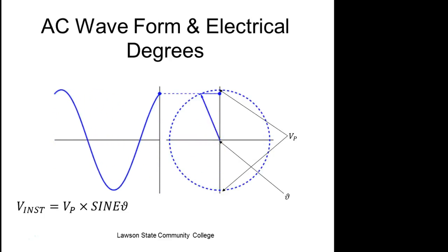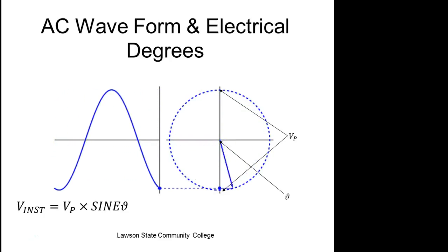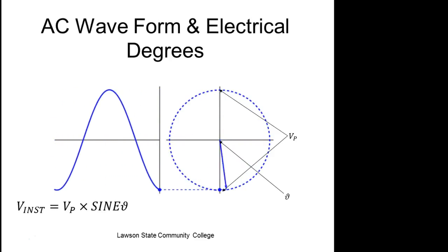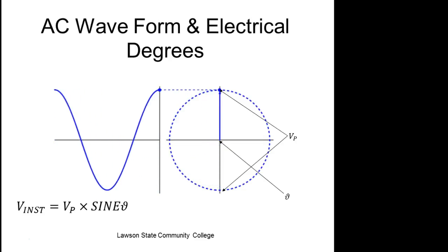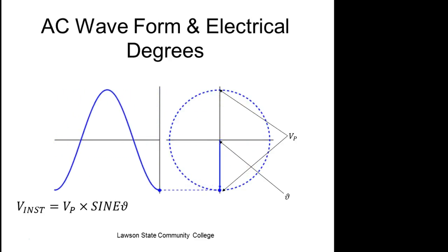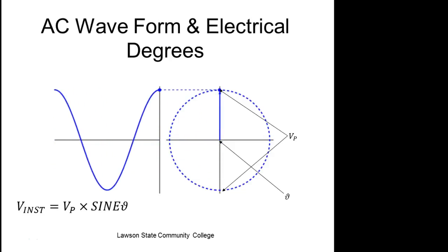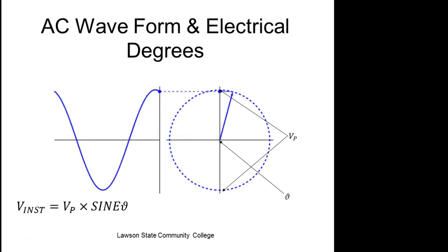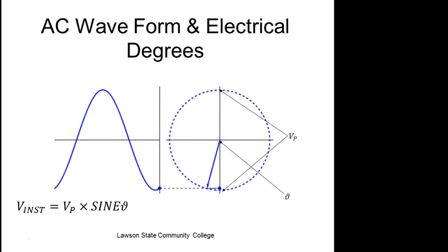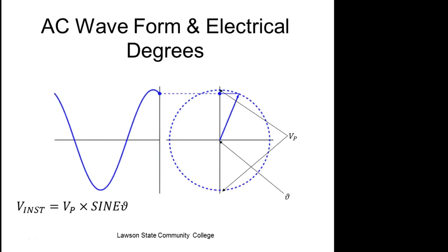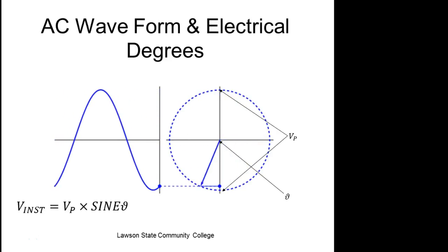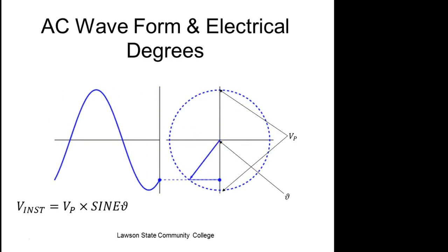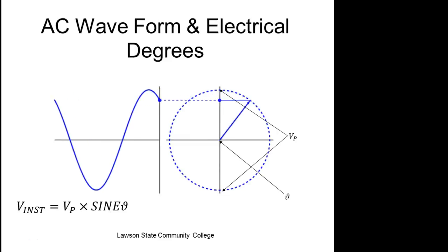So every 180 degrees, it goes back to what? 0. So literally, there's no current in the circuit right here. And these lights right here are flashing 120 times a second. It changes every 8.33 milliseconds. But luckily, the refresh rate of our eyes, we'll call it that, is not that fast.